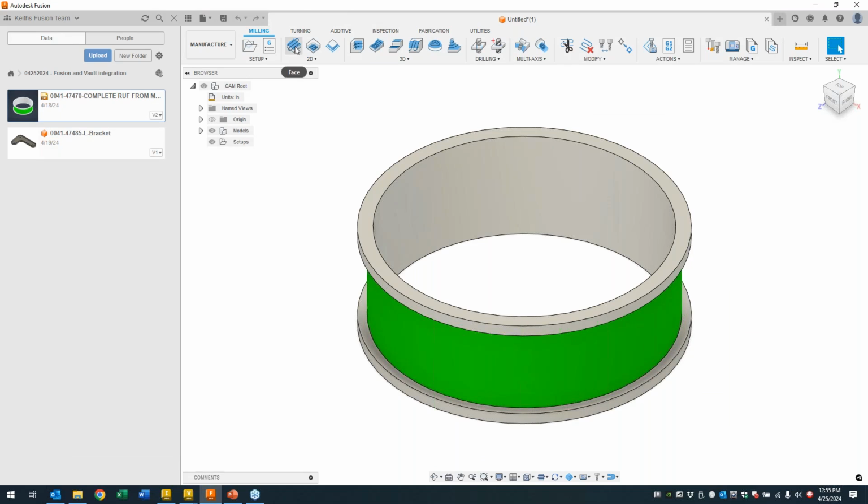A lot of these other tools, as far as doing facing operations, whether it's 2D adaptive steps, doing clearing or contouring, all of these function almost exactly the same as they do in Inventor. As far as the steps required and the options available, there's really only a small handful of additional functionality inside of here that you don't get on the Inventor side.